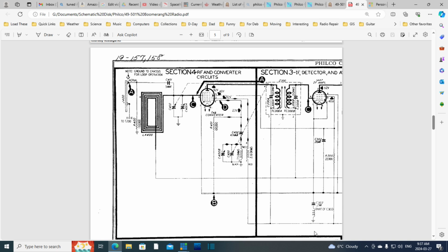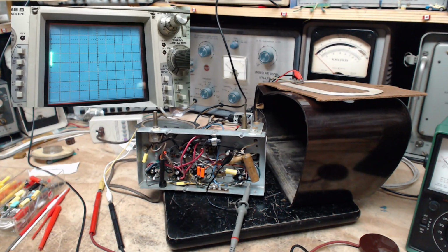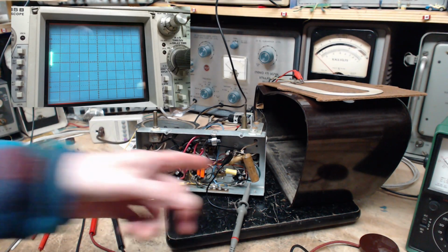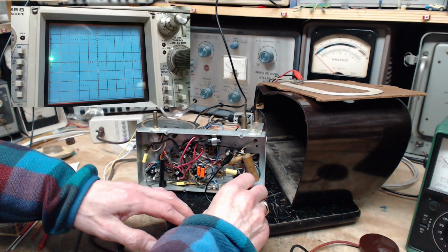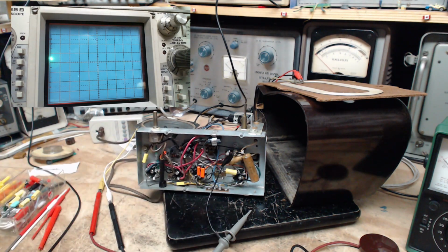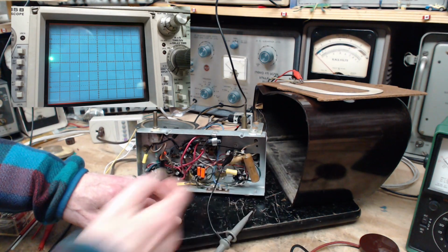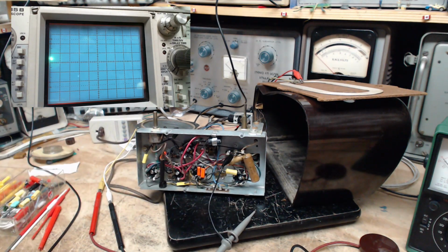I don't know. I'm not thinking anything good up here at all. Yeah, I gotta stop. Now I think all I'm left with here is to cut one leg off the capacitor and continue testing it. Ultimately I could put another capacitor in there and see if the radio works better. That's a way to go. I could even leave this one connected and just hanging out, leave one side connected.